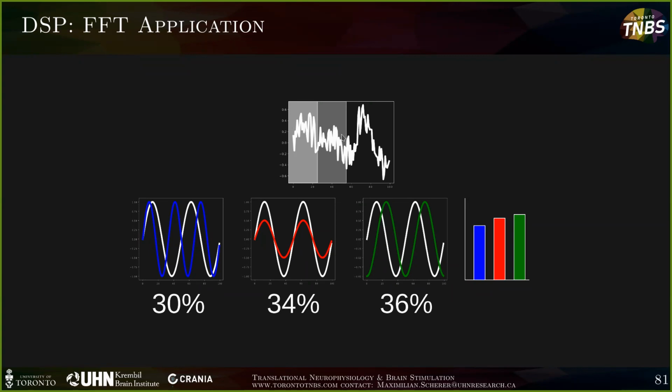So if we took two windows and did our FFT and derived our power spectrum density from that, and we average across those, we're going to get closer to the equal distribution that we had beforehand with the non-noisy signal. If we provide it with more data again, it's going to be even less noisy, and we're going to get even higher quality results. But that's assuming that we did multiple FFTs and average across them, not providing the data in one single chunk.